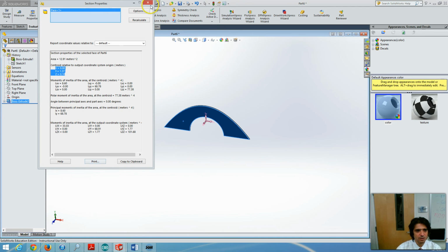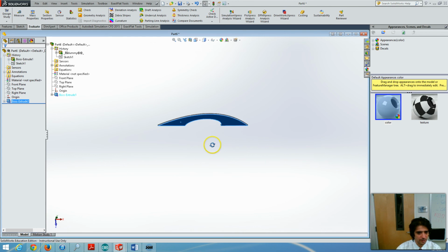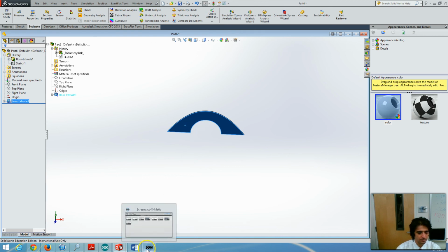Right, so this will be all for this recording and for the sectional properties of materials section. Very simple to use. You never need to use the Steiner theorem again. Just draw the proper cross section, select it either as a sketch or as a face. That concludes this presentation.